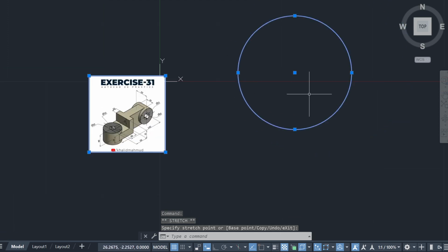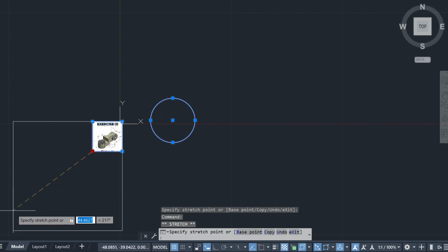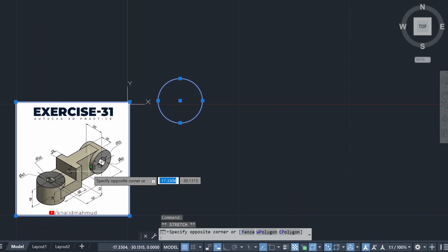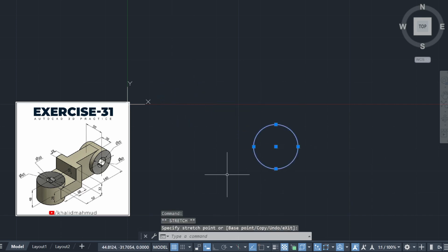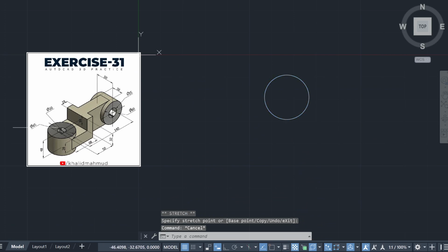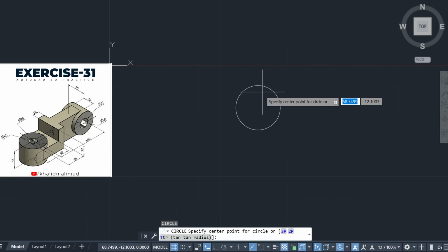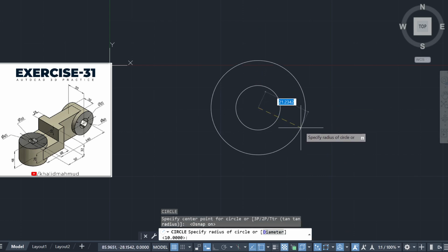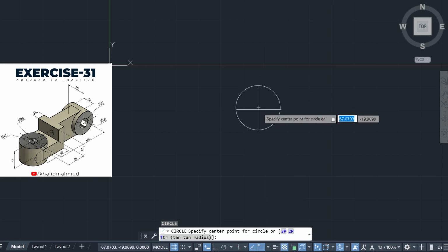So ito yung, this is just the interior triangle, the interior circle, no? So pwede sigurong lakihan ko pa ng konti, something like this. Kasi ito, interior circle pa lang to eh. So if I inputted the exterior circle na 65, and let's do that right now, I'll turn on my object snapping. Tapos, I'll create a circle from here. Kasi diba, interior pa to. Let's create a circle from here.